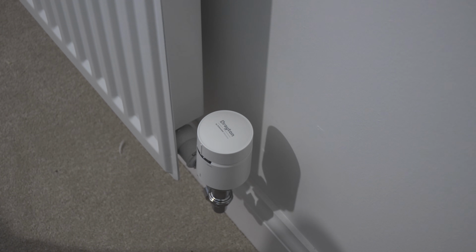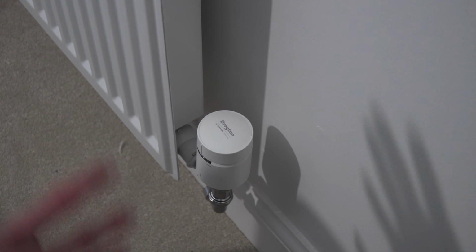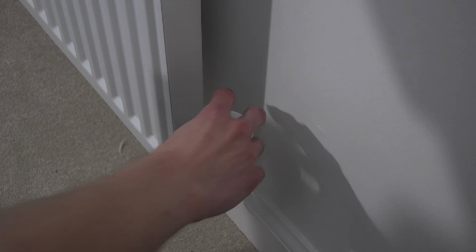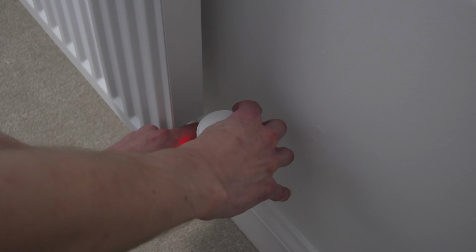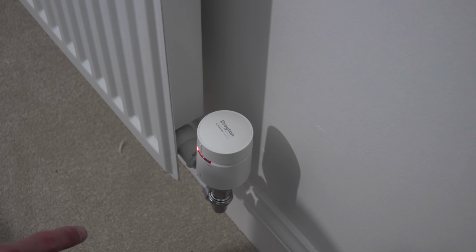Okay, so just quickly jumping in here. Bit of weirdness with the calibration there, because as we saw, it said on the app to turn it to minus and it would just calibrate, but it didn't. I've looked it up, and what you need to do is put it into calibration mode. You need to turn it to the plus first for a few seconds, and then the motor should start running. There we go. Yeah, that's the motor running now.